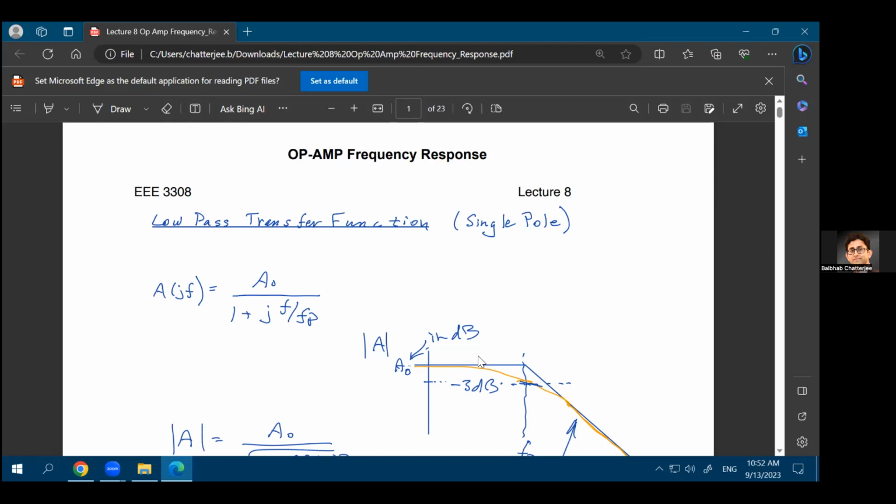As we have discussed, power is basically square of voltage. Why are we saying that power is square of voltage? Power is equal to v squared over r, or power is equal to I squared times r. So you see that the power varies as a square term with respect to your voltage. If your voltage increases 2 times, the power would increase 4 times. If the voltage increases 10 times, the power would increase by 100 times. So power increases as a square term of the voltage.